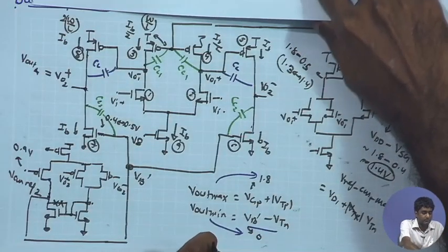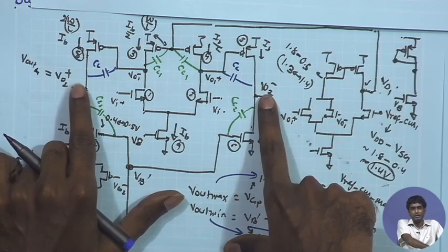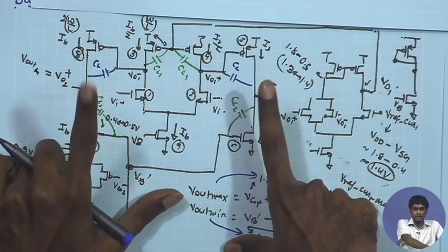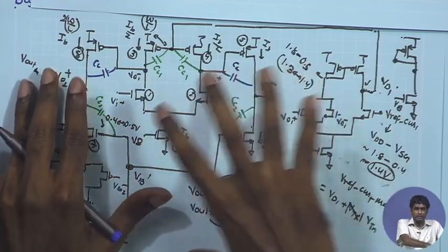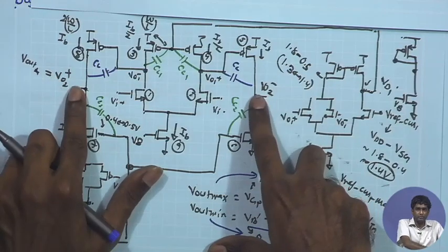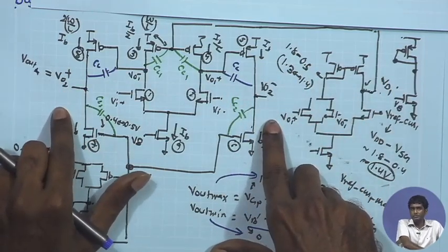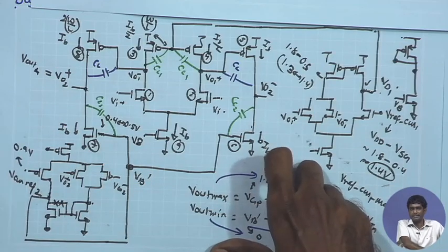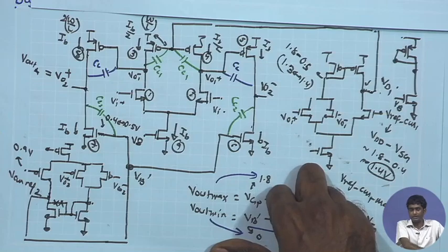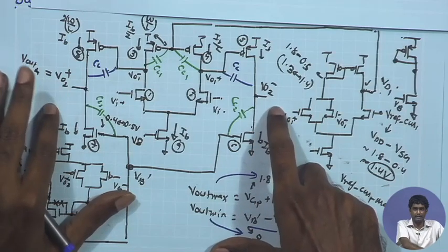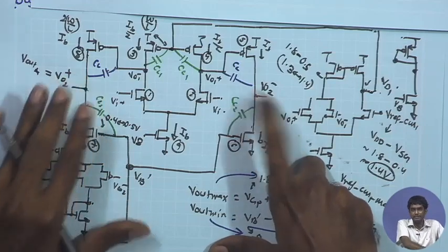And in general, the second stage will also have load capacitance because of the next stages. When you are applying multiple stages of amplification, this will also face load capacitance because of the next stage. So, anyway, you will have a CL over here, which is determined by the input capacitance of the next stage amplifier, which can be significantly large, a few picofarads as we have seen in our examples. Therefore, this is anyway a pretty large load capacitance, which can be significantly larger than CC.